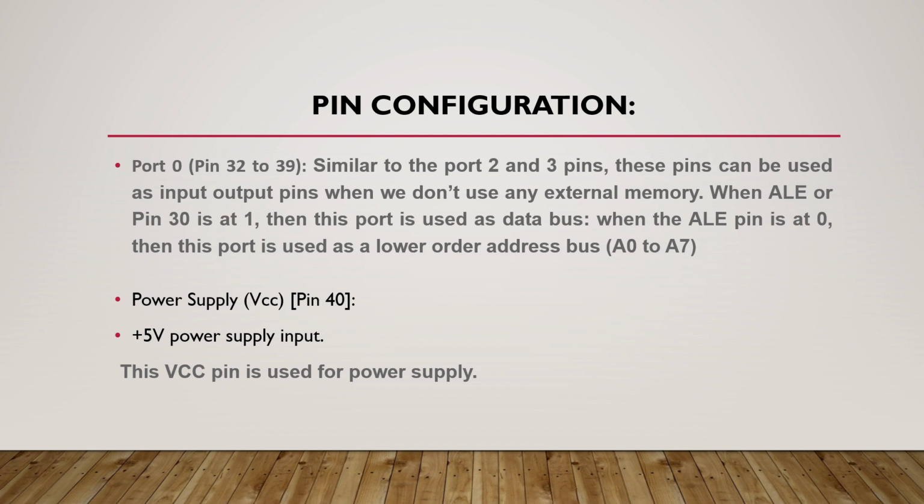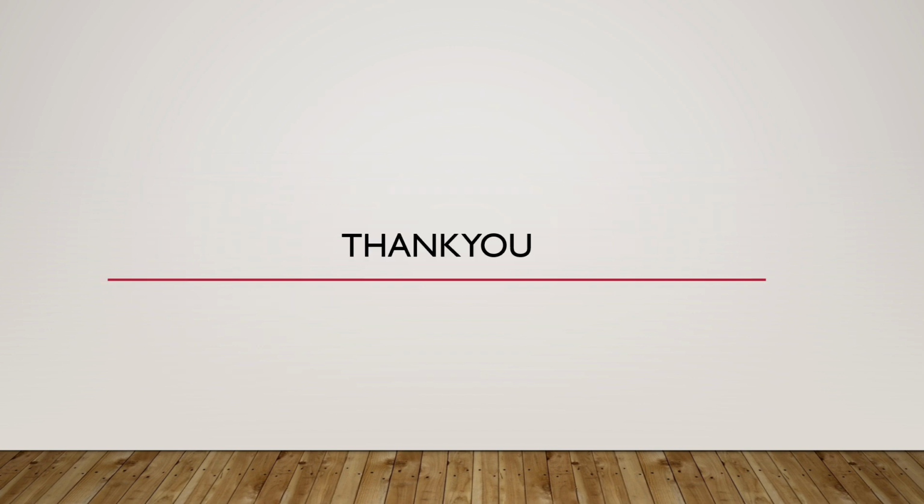Okay, next we have pin 40, which is the last pin. It is the power supply pin, or VCC pin. Whatever voltage we use in the 8051 microcontroller means 5 volts only. A 5 volt power supply input we are using, and this VCC pin is used for power supply only. So guys, these are the 40 pins we are using in the 8051.